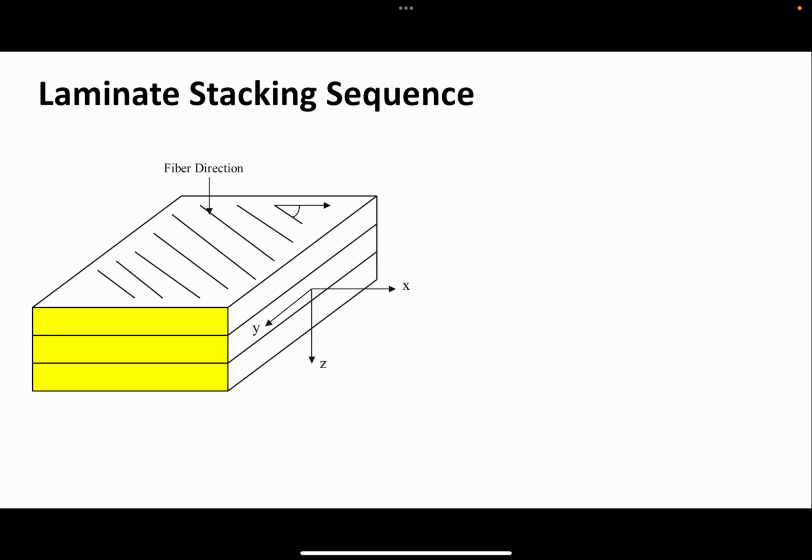For example, this is your ply. This is your 0 degrees. So then the other layers would be composed of 0 and 90 degree plies. Only those in some combination, it's called a cross ply laminate. And then quasi isotropic. What does that mean?